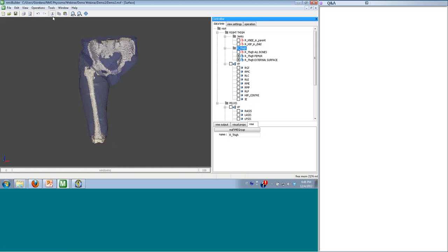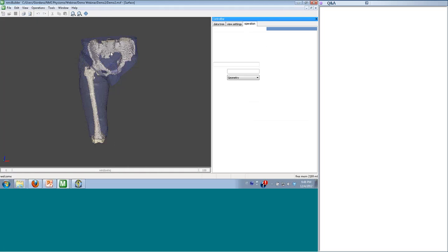And this particular feature can take into account the multi-surface body. So, for example, here I have defined different density for the hard and soft tissue, and now I'm going to calculate the global inertial properties of this particular multi-surface body. So, operation, measure, compute inertial tensor, and here I'm ready. I just have to pick OK. I'm not going to do it for time limitation because it's going to take some minutes. If the user assigned density, it will take this into account. Otherwise, if the user does not set the density, a default density will be taken for this particular calculation.